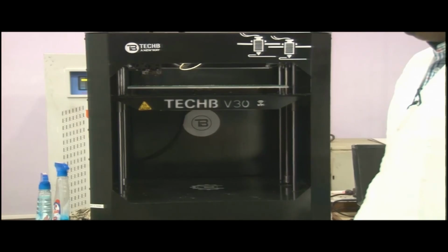The precision and smoothness of the printed models is also influenced by other factors such as bonding force between the layers, is it lower or is it adequate, then the weight of the upper layers that squeeze upon the lower layers, and printing problems like warping, misalignment, shrinking, shifting of layers. These printing defects might be there, all those things could be there.